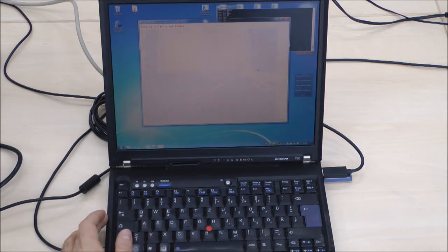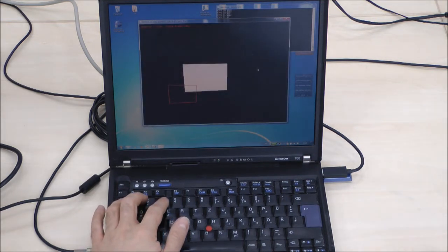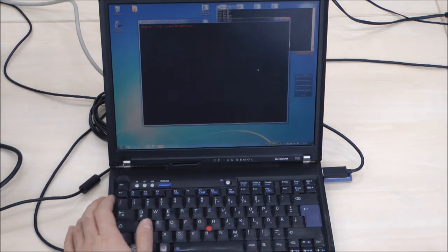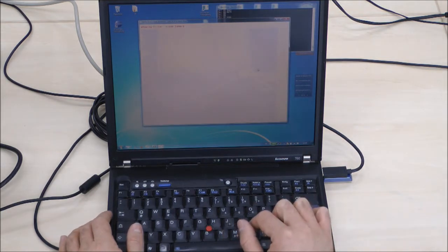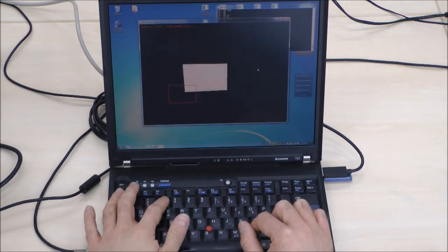Here you can see TouchD with a loaded XML config file. By pressing the number keys on your keyboard, you can switch between the different filters available in the config file. The keys are assigned to the depth level of the filter in the chain. So 0 is the first filter in the list, 1 is the second, and so on.